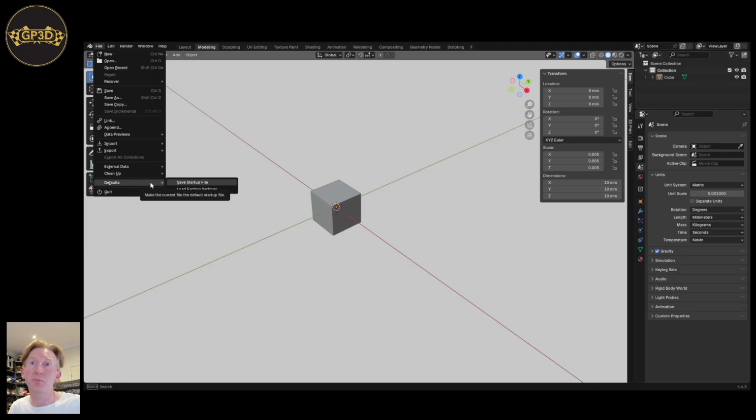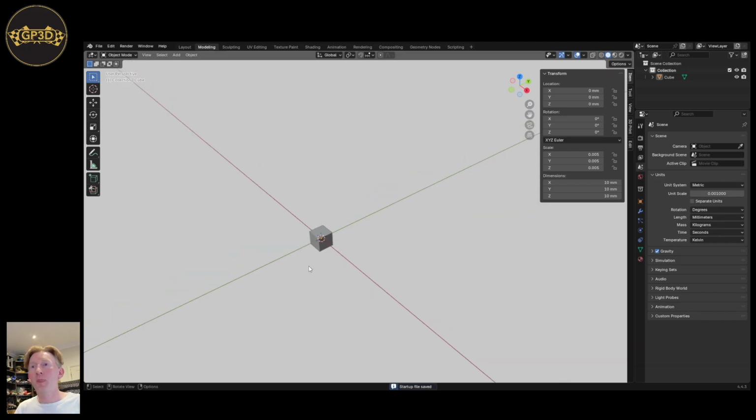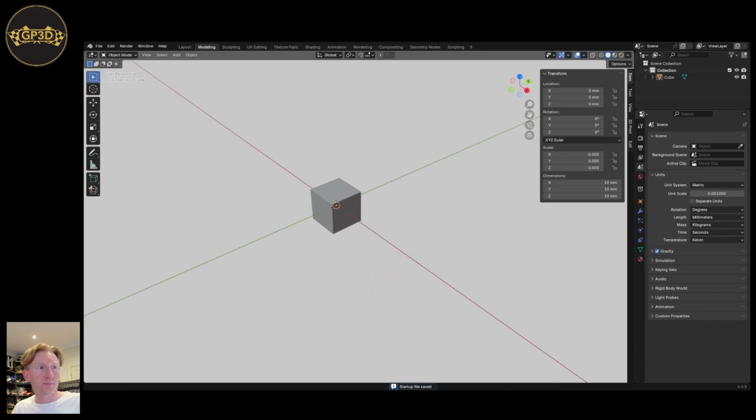If you just want to open a fresh Blender file again and see the default factory settings, you can, and that'll only be saved once you do another Save Startup File. If you're happy with a certain configuration and setup, you can overwrite your previous startup with your current configuration. So very important: Save Startup File. Cool. Okay, so that's the first part of this video where we installed Blender and configured the environment for our purpose.